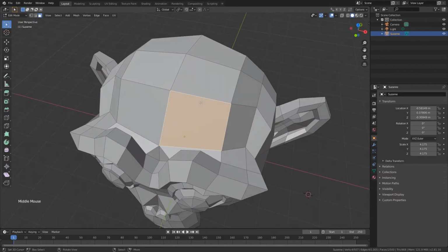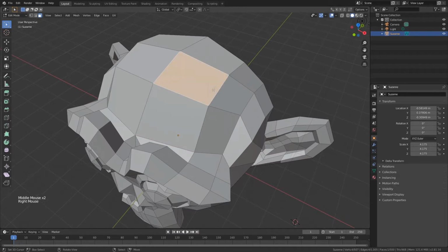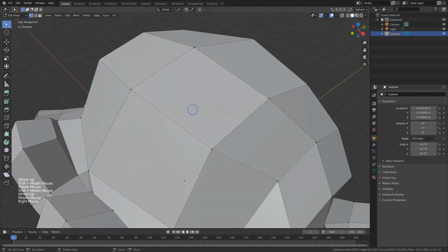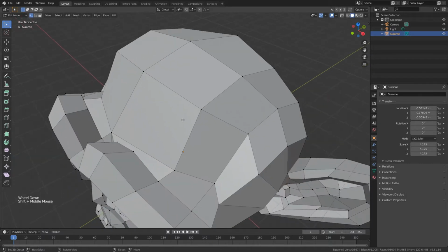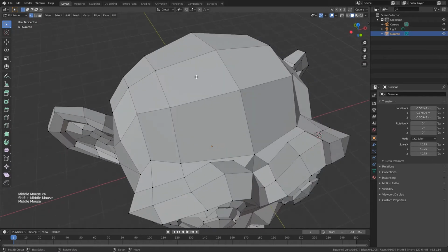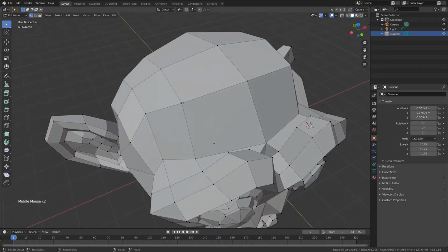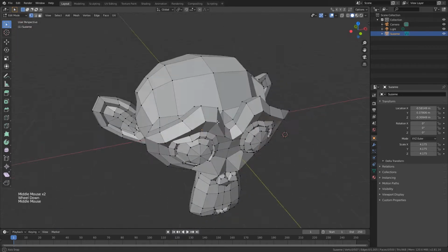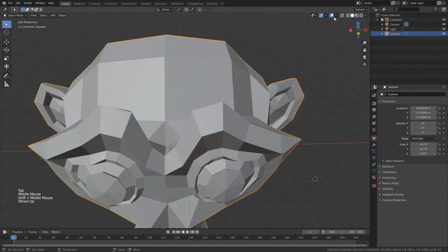In the entertainment industry, all the models are made of polygons. Now these polygons are made of 4 edges and 4 vertices, and you can select them and manipulate them, shape your model according to your need. And a face could be 3 vertices as well, but it's a very standard practice to keep your model in polygons to keep the topology very clean, and for the calculation of many other processes like skinning and shading and all.